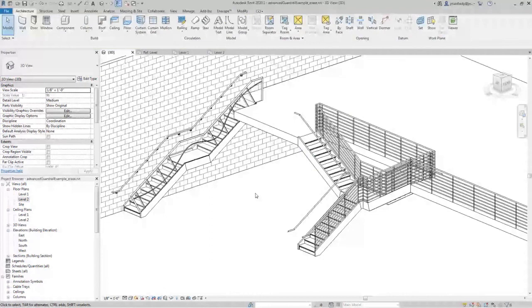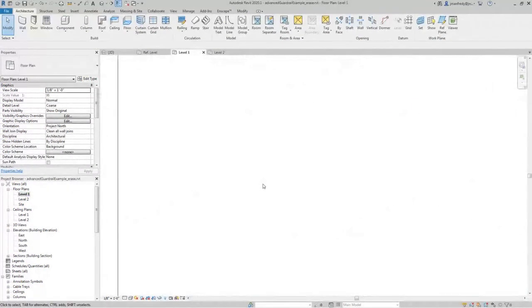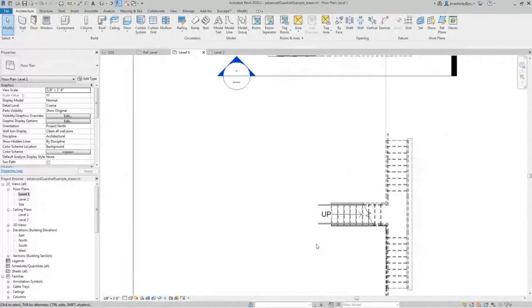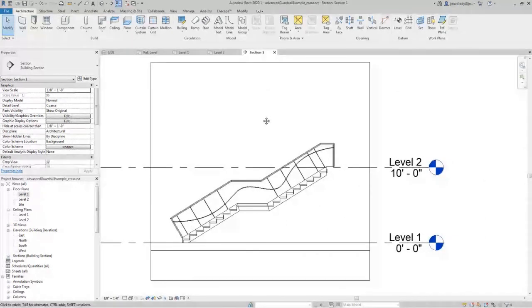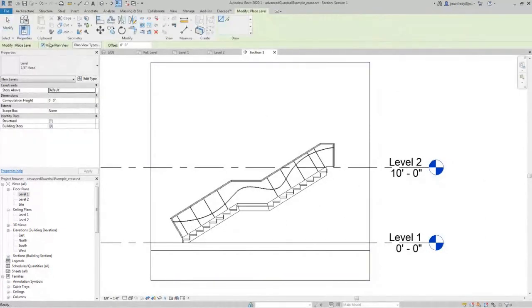Your task is to go into your projects and create level tags where all your different heights are happening. Like if you want to stand on a certain place in your topography, you need to go into Revit, into levels here, turn this off, turn that off, and create a level tag somewhere.